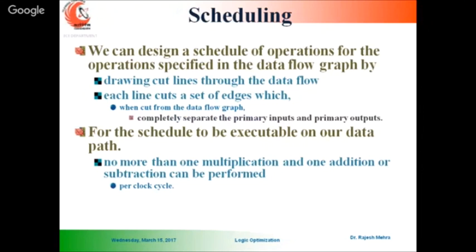Now next, you have to schedule the operation. As I told you, the major parts of your HLS, high level synthesis, are that you have to schedule and you have to bind. First part is scheduling after DAG. Once DAG is done, you have to schedule.